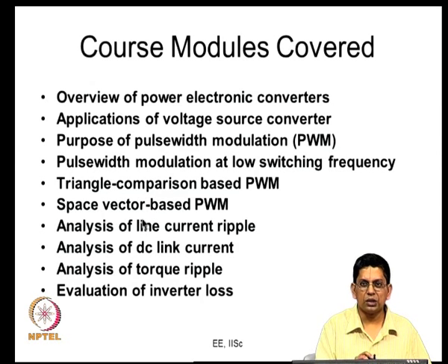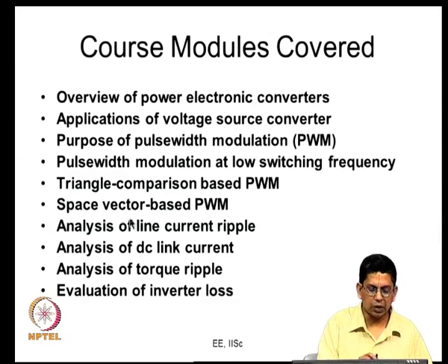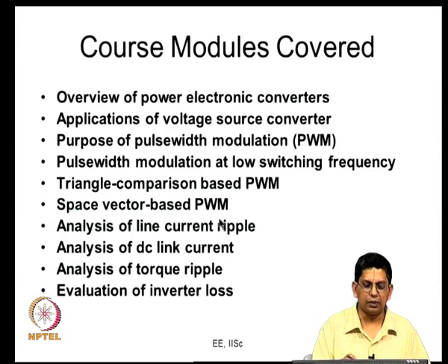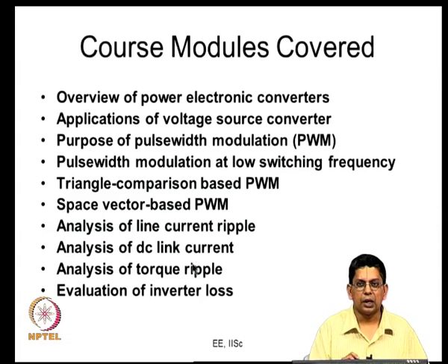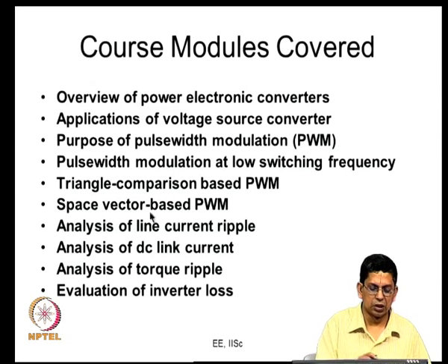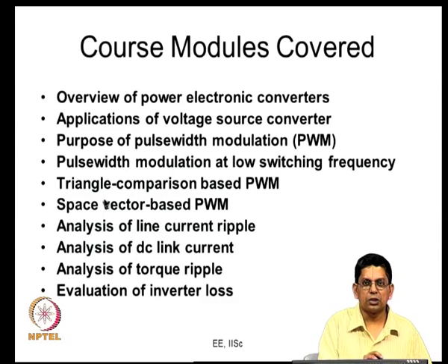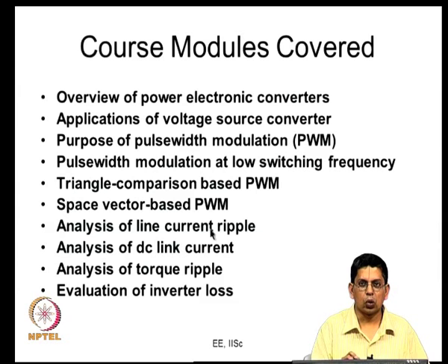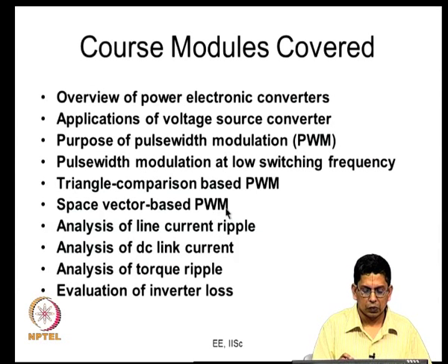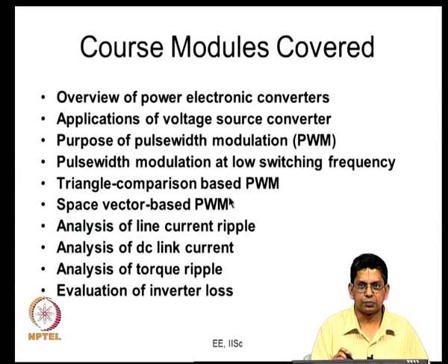But the more recent advances show that the space vector based PWM is more general than the triangle comparison based PWM. There are what are called advanced bus clamping PWM methods, which are space vector based PWM methods. The waveforms produced by these methods require this kind of space vector approach, or rather you cannot compare 3-phase modulating signals against a triangular carrier to produce the same waveforms produced by the so called advanced bus clamping PWM methods. So, this is more general than that.